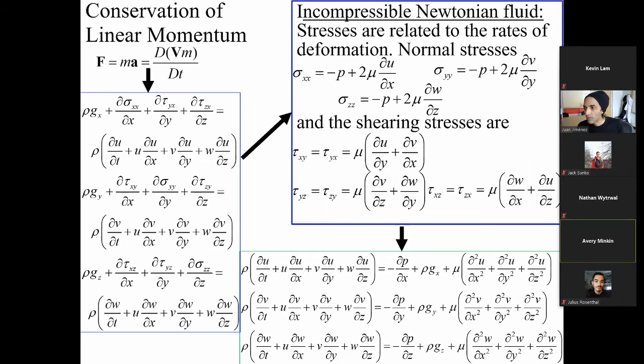Okay. For the continuity equation, you can use that with compressible flow. Yeah, as long as you have the rho inside the differential, because the density would change with location. So you have to have it inside the differential. Okay. All right. Thank you.